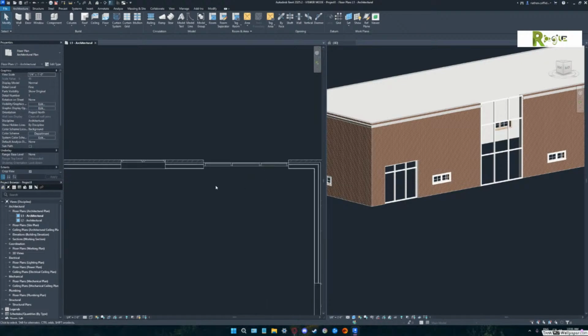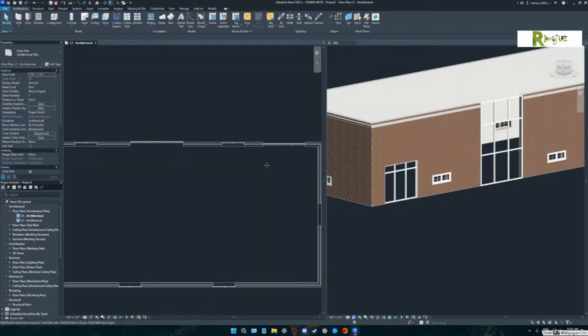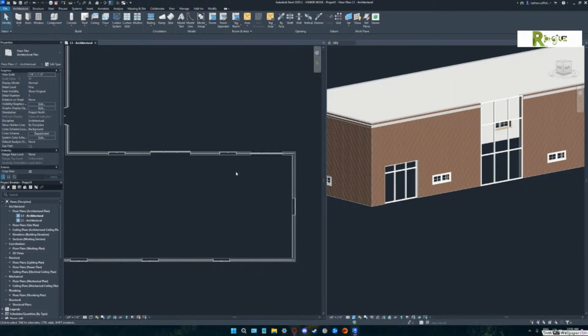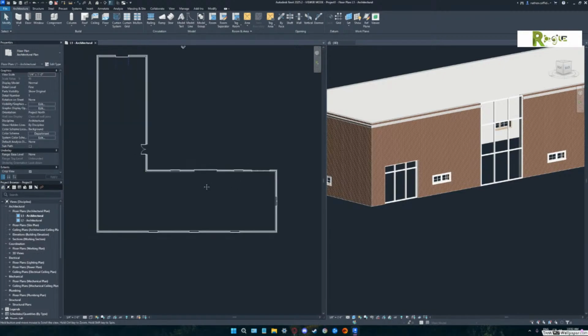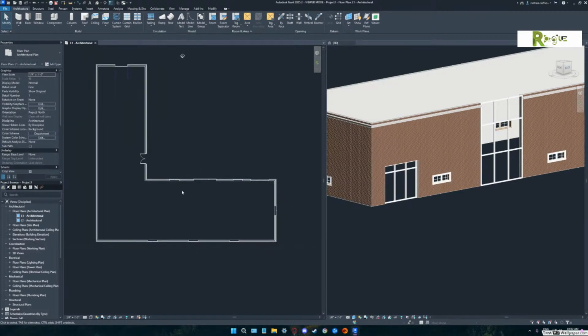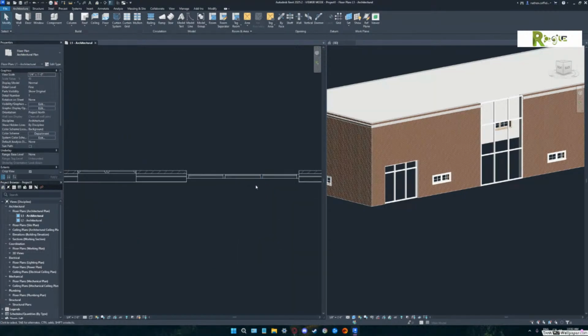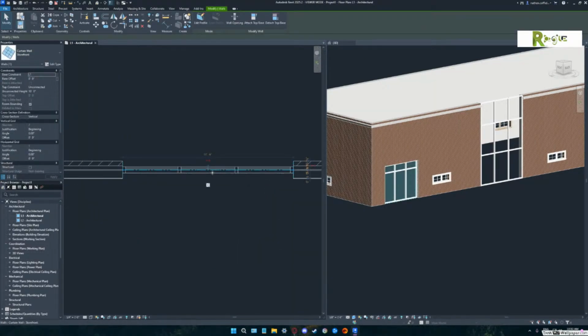So where most people go wrong is if they're doing a commercial building, there's very few windows in a commercial building. Most of them are actually walls, which are curtain walls. So let's take a look at what a curtain wall looks like on properties. So if you zoom back in there and got on top of that curtain wall that we just drew, yep, selected it. Now, the reason most people get frustrated with those curtain walls is there's several different things. We're going to have to play with how you select them, but you've got it exactly. You've selected the curtain wall storefront.